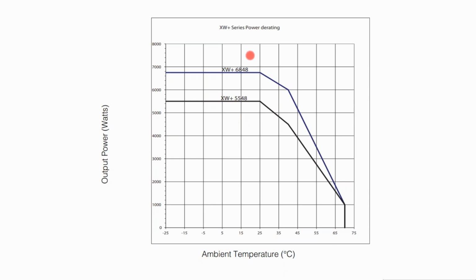In fact, here's the Schneider inverter, and what you can see is once the temperature gets above 80 degrees, the efficiency of the system begins to drop. And so it is a good idea to air condition your inverters. It's not that you have to, it's that their efficiency improves if they're kept cool. Their life improves if they're kept cool. Same thing with your batteries.